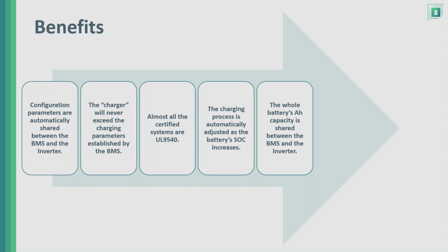As I mentioned before, the 4 batteries now total 20 kilowatts, and that information will be shared between all the batteries connected in the closed loop. If we have 4, the master battery will know that the whole bank is made out of 20 kilowatts, and that's the number in terms of amp-hours, which will be about 400 amp-hours, sent to the inverter.